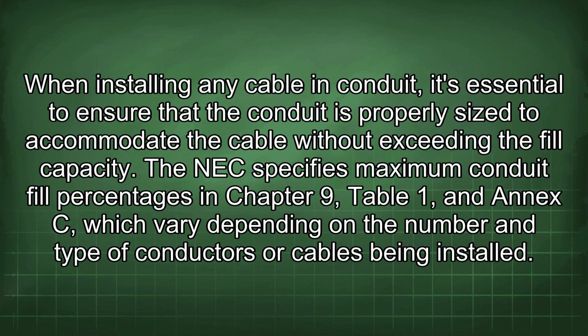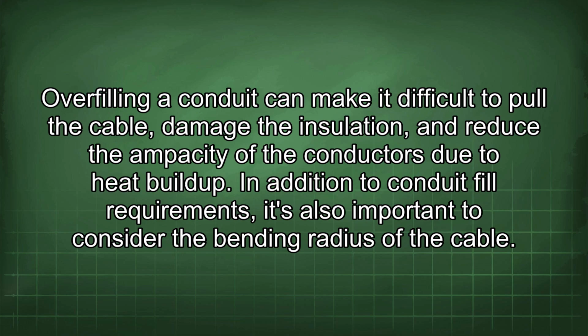When installing any cable in conduit, it's essential to ensure that the conduit is properly sized to accommodate the cable without exceeding the fill capacity. The NEC specifies maximum conduit fill percentages in Chapter 9, Table 1, and Annex C, which vary depending on the number and type of conductors or cables being installed. Overfilling a conduit can make it difficult to pull the cable, damage the insulation, and reduce the ampacity of the conductors due to heat buildup.